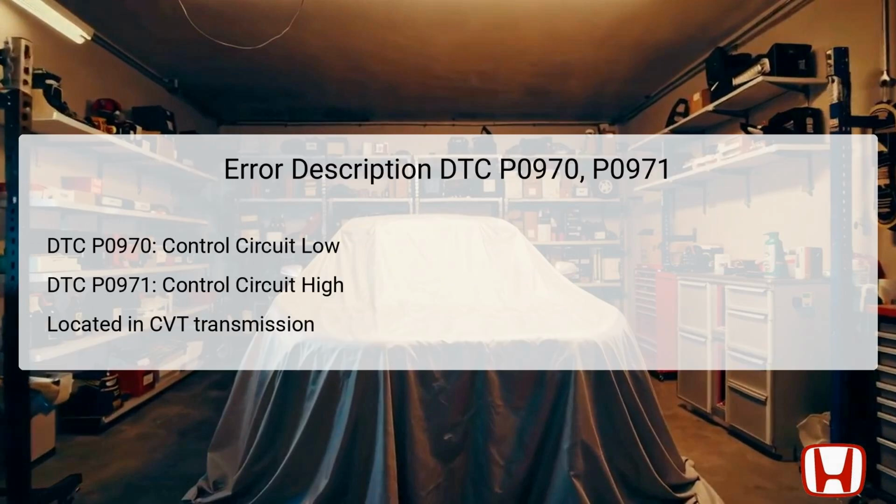The error codes P0970 and P0971 specifically relate to the control circuit of the pressure control solenoid C in the continuously variable transmission CVT of the Honda Civic. DTC P0970 indicates that the control circuit is receiving a low voltage signal, while DTC P0971 shows that it is receiving a high voltage signal.